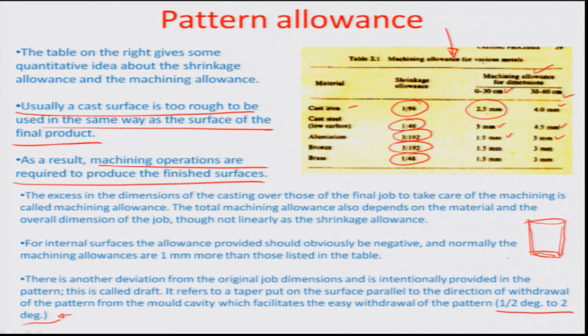We will talk more in the next module about how we further design the mold, or how we design the runner and the riser, which are the two most important things to ensure that the metal flows well and flows into the cavity before it freezes, and also rises on the other side to indicate that the cavity is full.